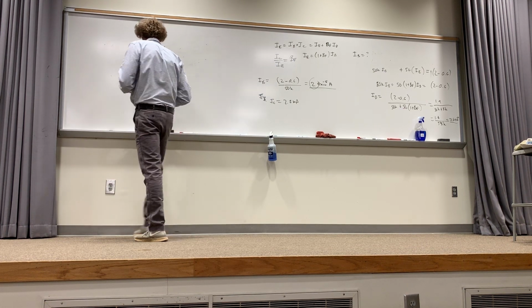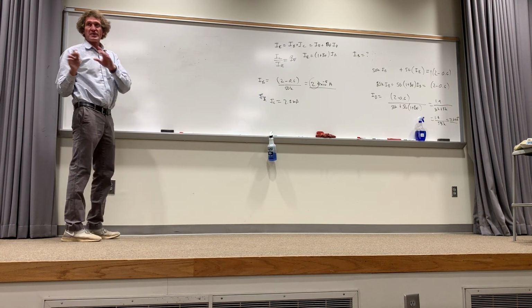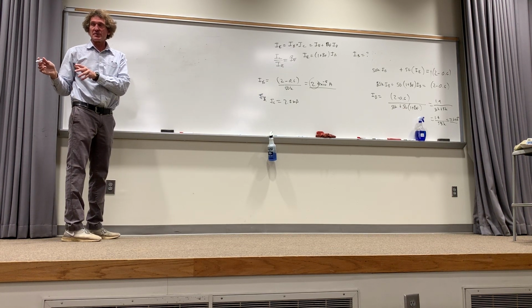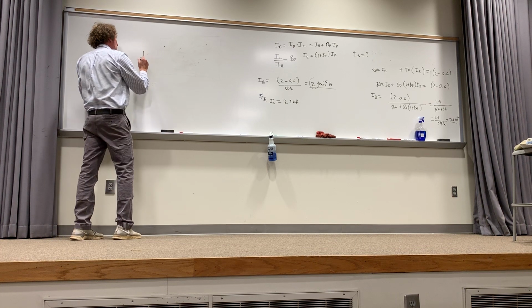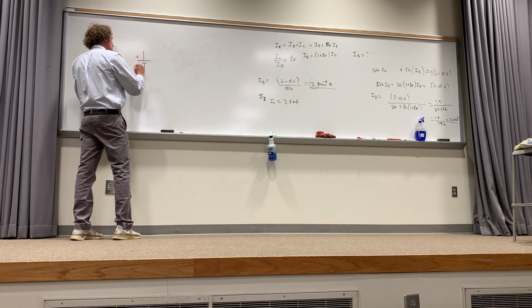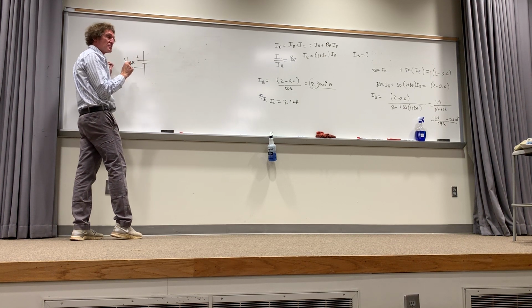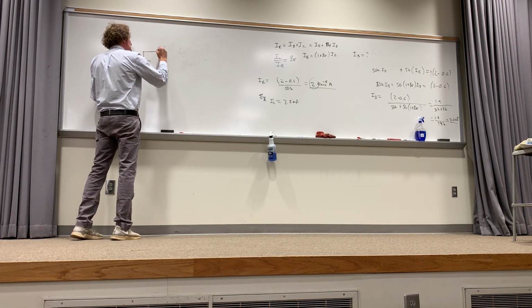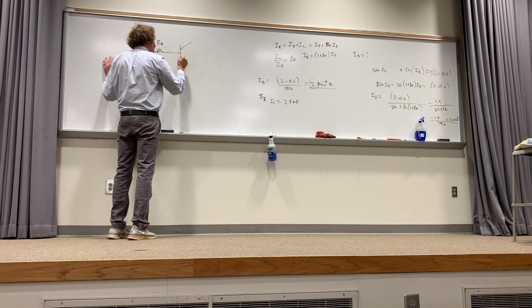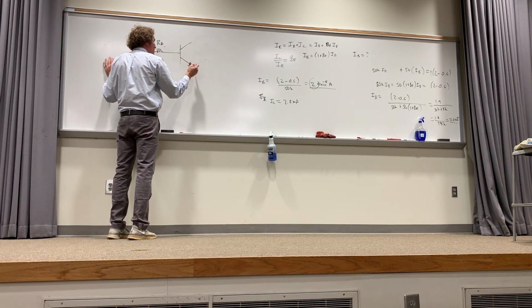I'm going to do this so you'll see it. Write this down just as a template so you understand. In general, if you have a voltage here, plus or minus, I'm going to call that VBB. You can call it what you want. This is going to be R sub base. I'm only going to give you NPNs, that means the arrow's pointing out.